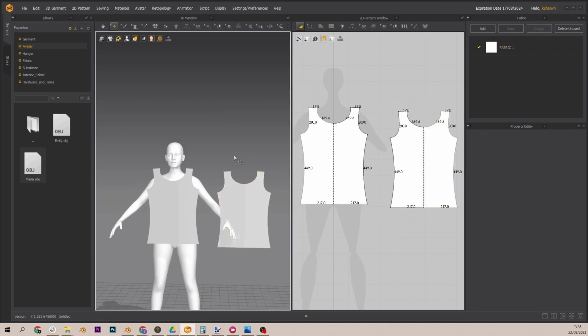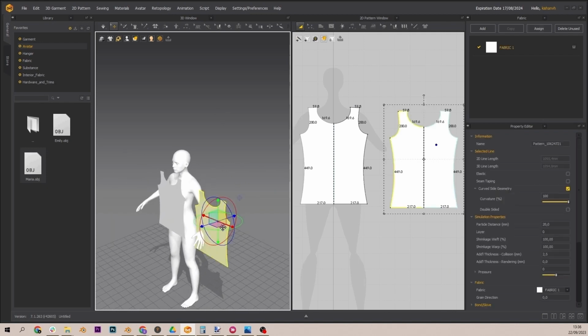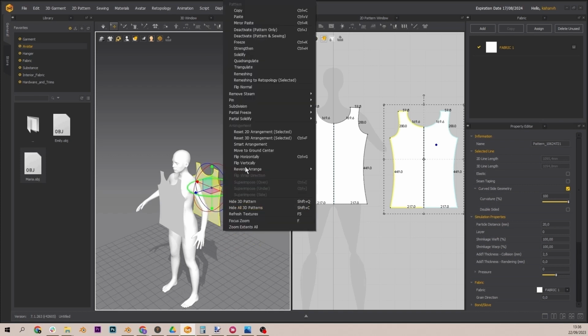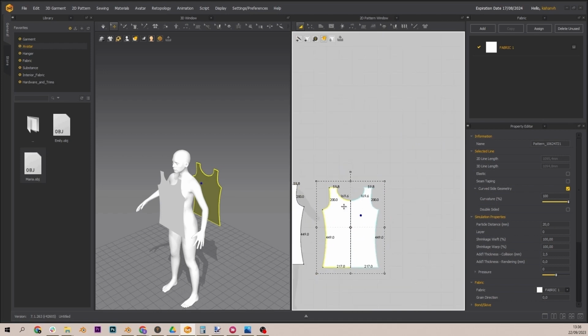Select the Select and Move command. Here you can move and rotate shapes. Holding and dragging the green ring allows rotation around the axis of the green arrow. Ensure the white side of the surface is facing outward. Right-click, choose Flip horizontally.